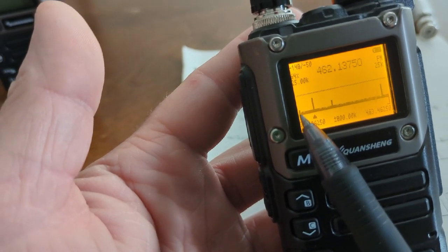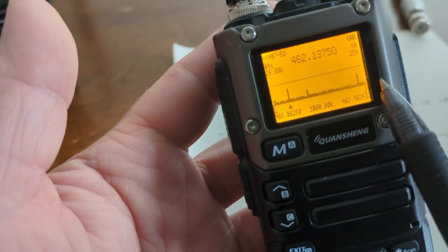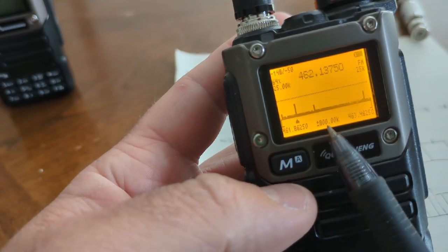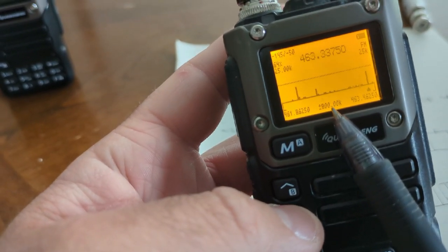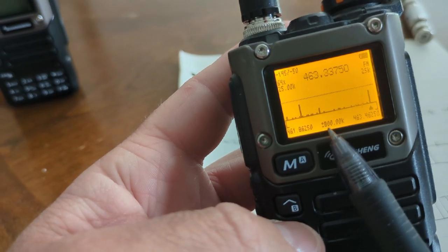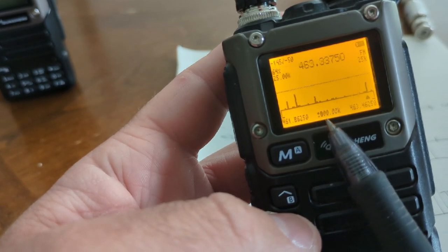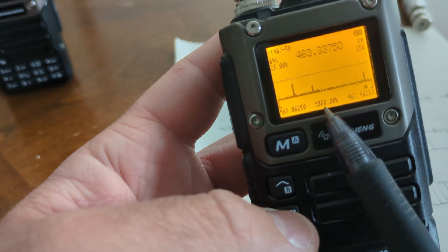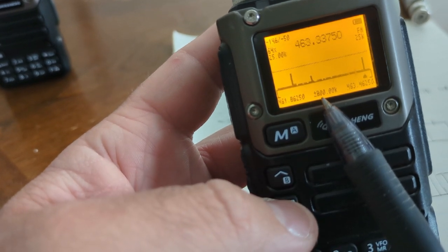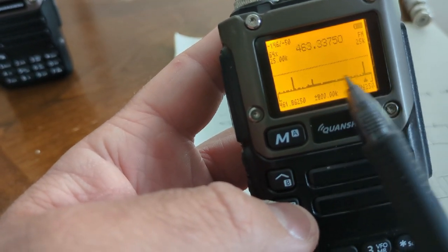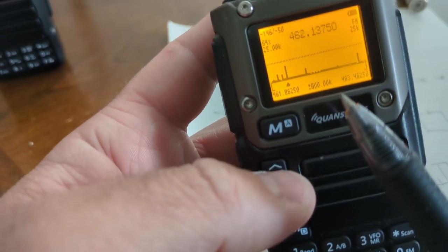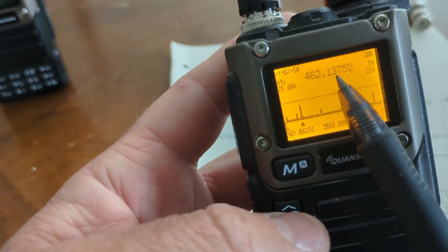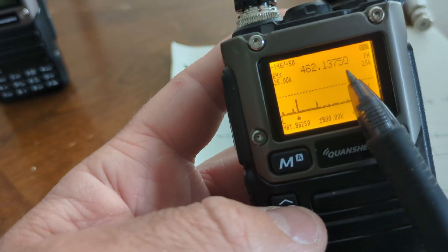This is the leftmost edge of my graph and the rightmost edge of my graph. And if I hit the up and down arrow, I can scroll left or right. And then this is how much that scroll is. It's plus, right now, if I click the up button or down button, it will move me 800 kilohertz to the left or right, looking at a different section of the spectrum, right? So this is whichever signal is strongest right now, indicated by the arrow.